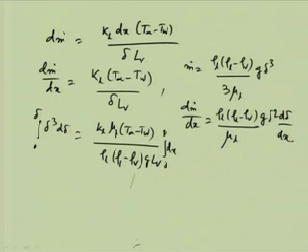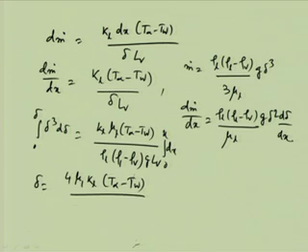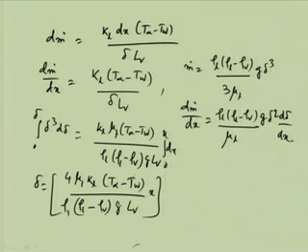This is from 0 to x, and this gives us that delta equals (4 mu L K L (T infinity minus Tw) by (rho L minus rho V) into rho L into G into LV) into x, whole to the power 1 by 4.